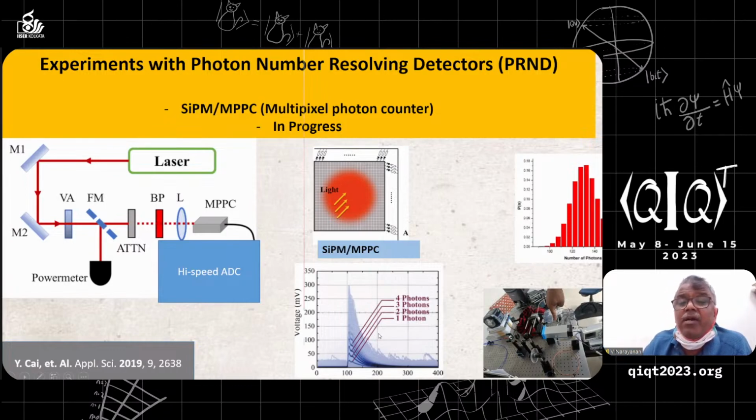Some of them are inbuilt, kept at something called TEC cooled, which is typically minus 10 to 20 degrees. If you get it from the manufacturer, they make it. Otherwise, you build your own TEC, keep the chip on this, and send the given light source. It can be a laser or a broadband source, like what I spoke about earlier, even an attenuated or weak coherent pulse, or even entangled photons.